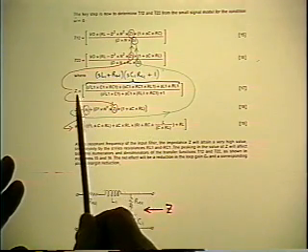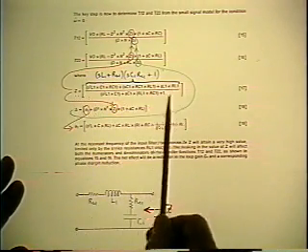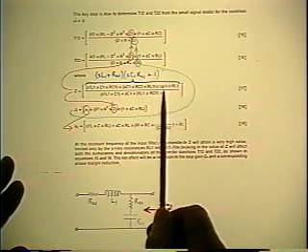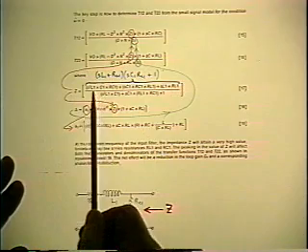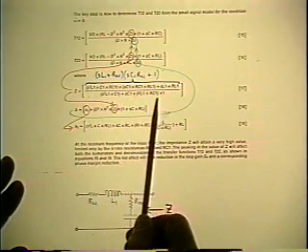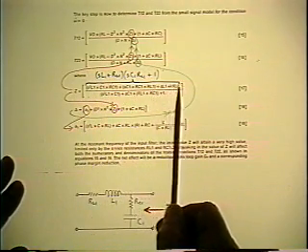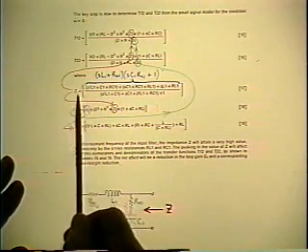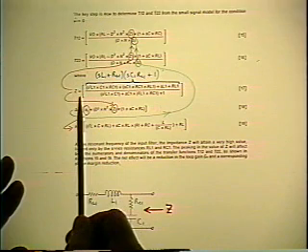What is the reference value for the impedance when you express the result as a ratio of polynomials? The reference value is the zero frequency value, which is what you get when you let all the S terms go away. What do you end up with? RL1. So he's got RL1 effectively as the reference impedance at the front end, which is the zero frequency impedance.